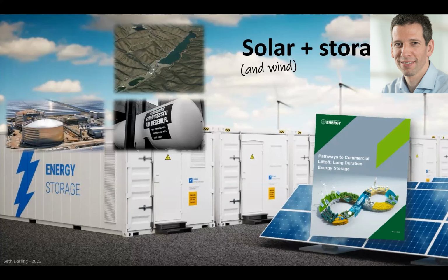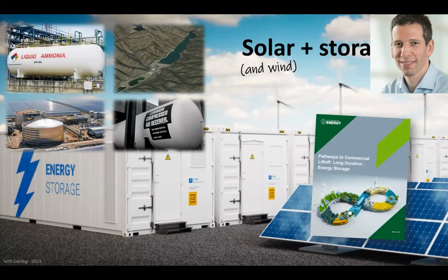This is especially useful with solar because you can use the heat from the sun, not just use solar panels to make electricity. And you can store thermal energy for, not forever, but think of giant coffee thermoses basically, where you heat up a fluid, thermally insulate it, and then 8 or 12 hours later, you can get that out as electricity. And then if you want a really super long time, you do chemistry, you make chemicals. You can make hydrogen or ammonia or other chemicals that can store it more or less indefinitely, and then extract the energy.